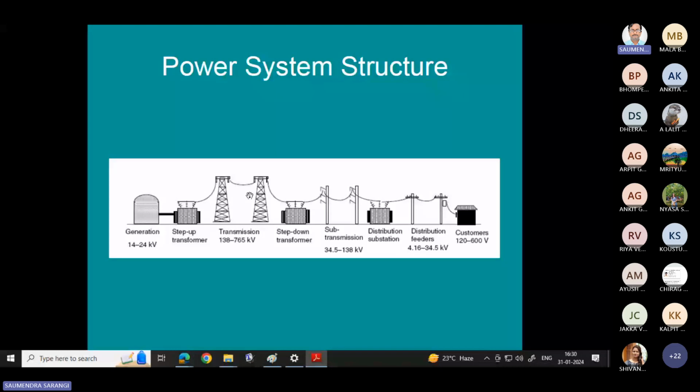The transmission system basically uses both voltage and current, whereas the distribution system uses only current. When we use both voltage and current, the relay detects the impedance of the transmission line up to which the fault has occurred, takes a decision that there is a fault, and breaks the circuit. Similarly, the other equipment we have, like inductors, transformers, and reactors, all need to be protected by differential protection.